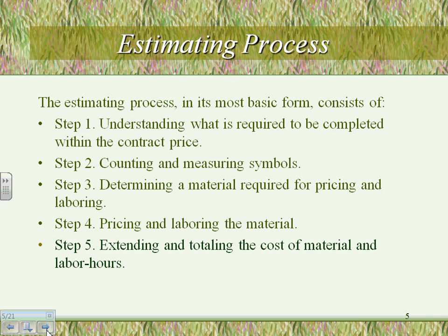So that's the last step. The last step, guys, is after you do the pricing, assign a price. Where do you get the price? Vendors or software. Software gets the price from the vendors. Where do you get the labor? Labor is organized labor, like NECA guys have standards where you can buy their labor units, or you can develop your own labor units.